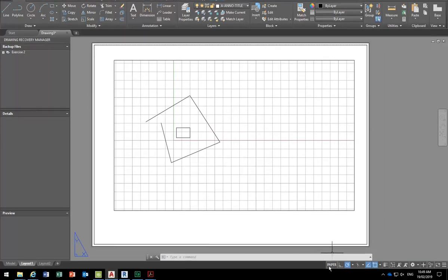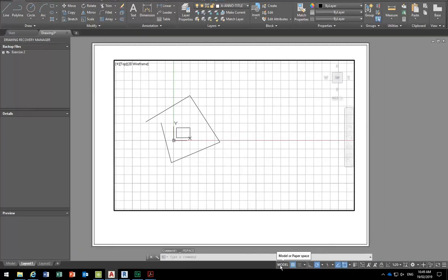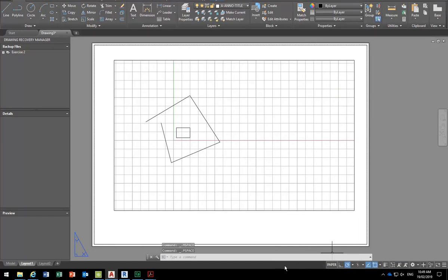Okay, so click on the button down the bottom that says Model, and that'll make sure you can double click outside the viewport as well. Yep. So that's the printable area for this PDF page, but I want to be a bit smaller than that to be safe for other printers. So I'm going to offset, and maybe I'll do it in 2 mil increments.